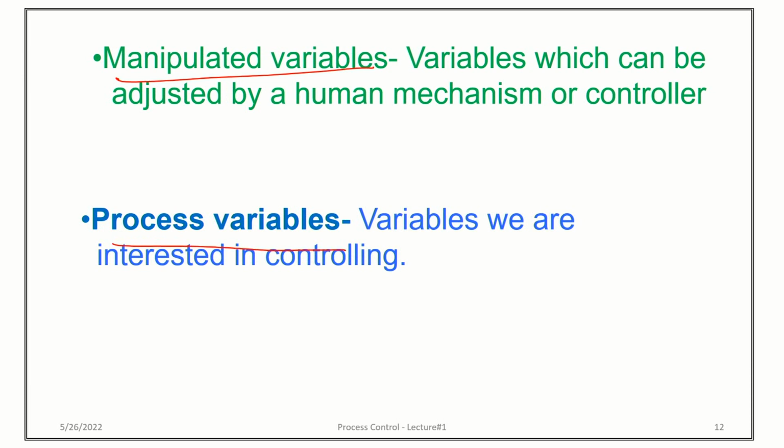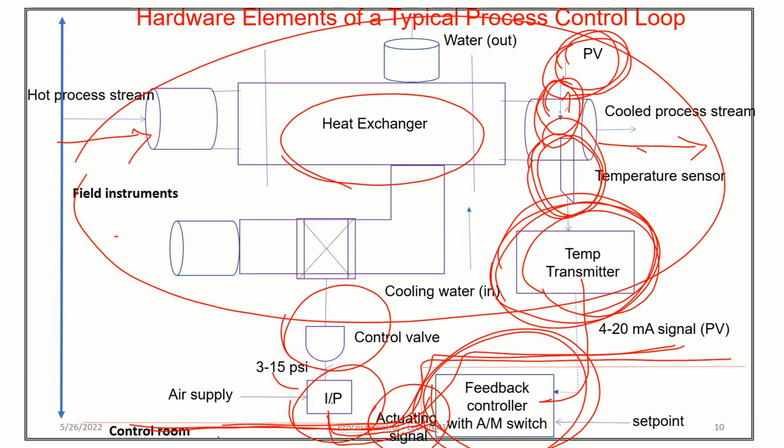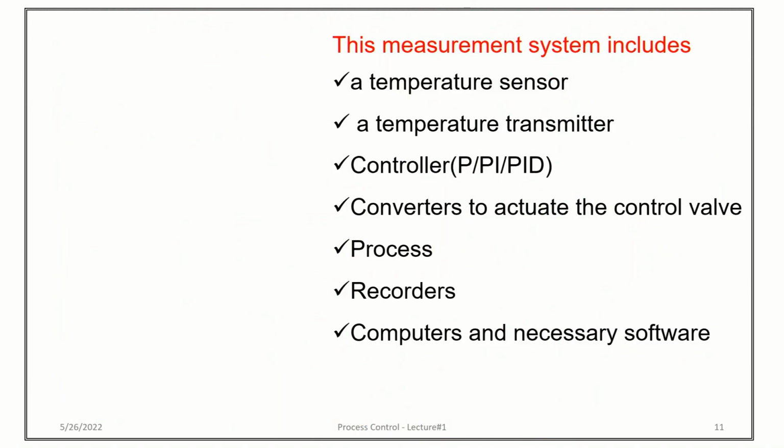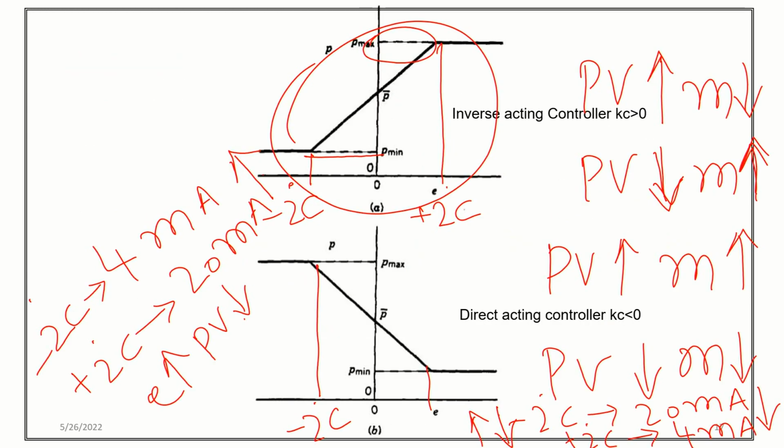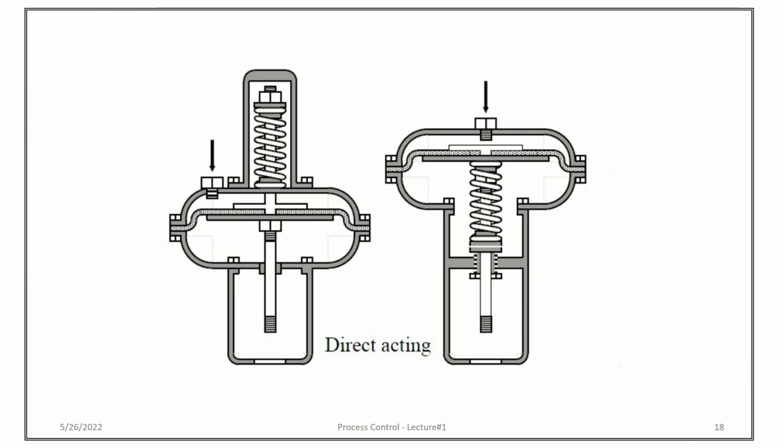Then coming to the next important component, which is called your control valve. The very popular example of any final control element is the control valve. Control valve is essentially a variable resistance to the flow of fluid, in which the resistance, and therefore the flow, can be changed by a signal from the process controller, because the controller output will normally operate your control valve through your electro-pneumatic converter or I2P converter.